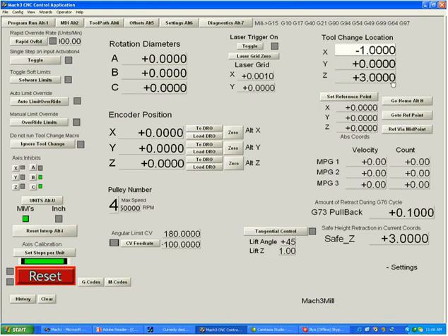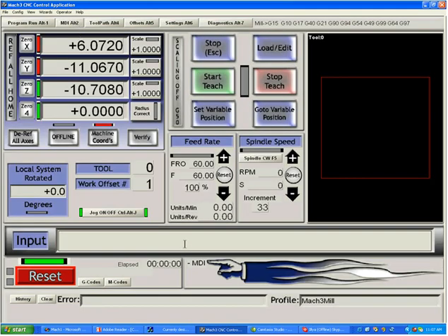And on the settings screen, let's set an X location of 10, a Y location of 10, and a Z machine coordinate of 0, which remember would be at the top of the Z stroke in most instances. Now if we type T01 M6, the M6 part of this command is going to execute the macro we just typed. And as we can see, the Z first goes to 0, the X and Y then go to 10.